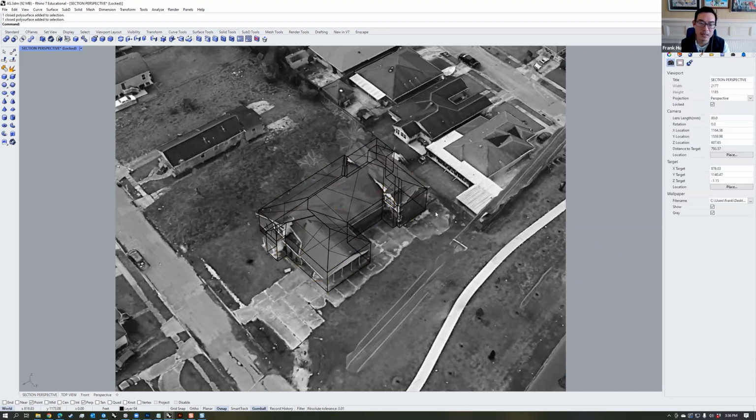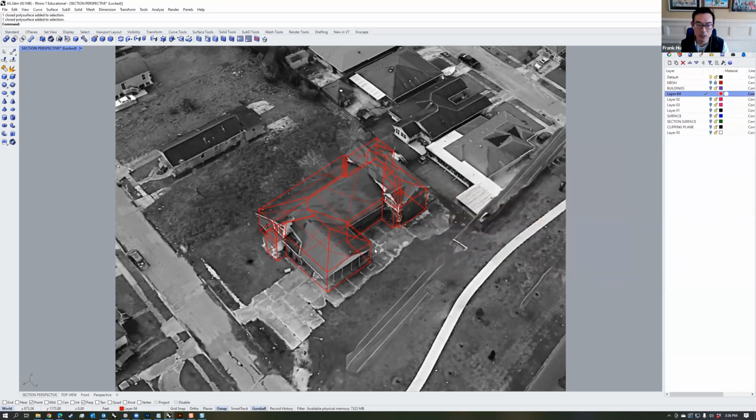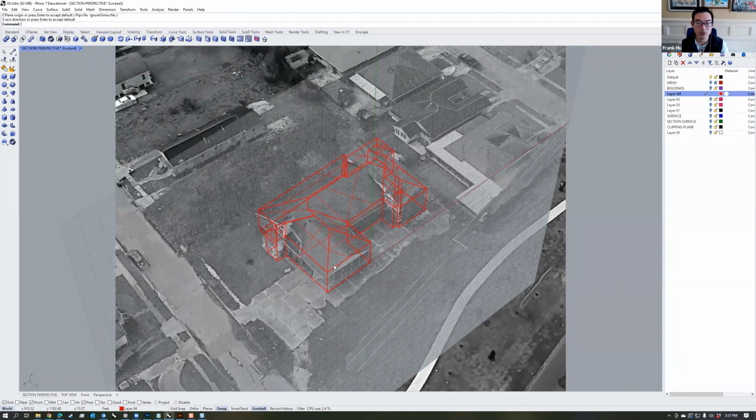One thing that comes in handy is to always make sure that you're working within the C-plane surface plane that you want to edit. Basically, let's say, for instance, right here, you can see this building face right here, and the roof pitch here actually extends all the way to the front of the face. So what you do is you type in C-plane in the modeling tool here. You choose surface in the C-plane options. Then you can pick any surface in the modeling world, like this one right here, for instance. Then you can set a C-plane right there. And so when you draw or you edit or anything, you can actually edit within that plane itself.